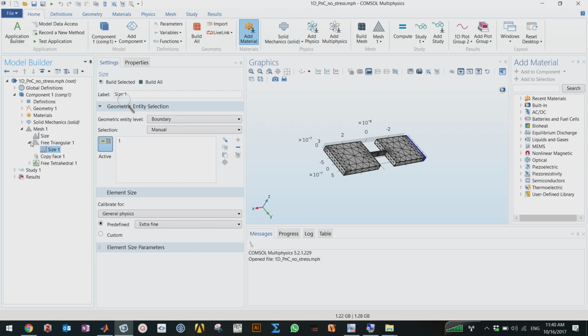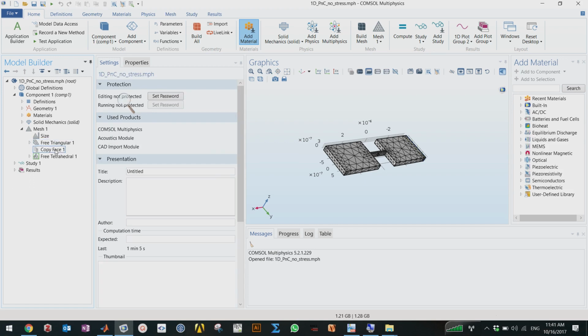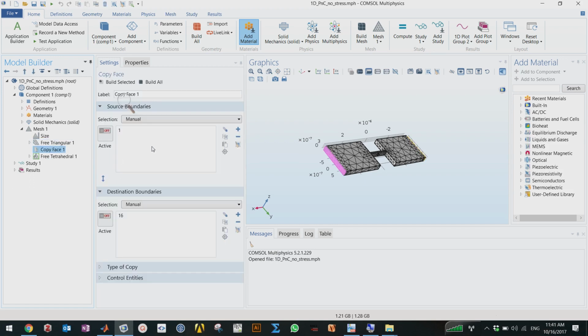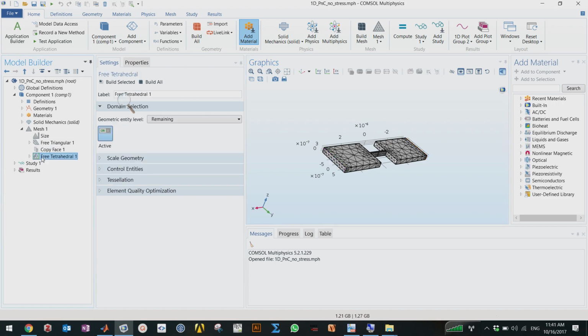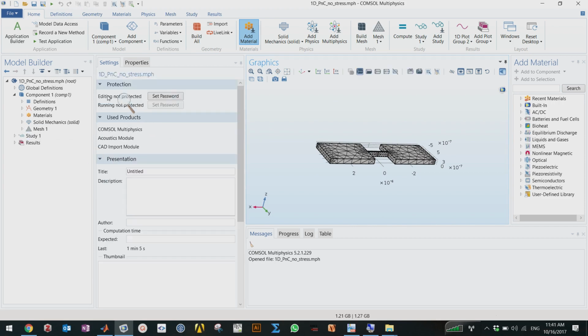And as always, I want to include the geometry nonlinearities because sometimes due to the sharp edges, some effects may happen. And then if I click study here, it's going to be very quick. So I will just solve for the modes of this structure with the boundary conditions being the periodic boundary condition, and you'll see different modes of this structure. And for example, here you see the convergence plot, so it's going okay, it's not oscillating and not converging.